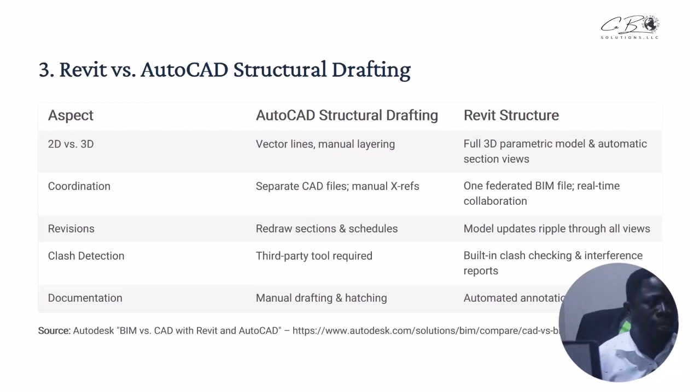Just some small steps. If you want your views, let's say your front elevation, these are not things we do manually in Revit. No, no, no, no. We don't do such stuff in Revit. Like you are done with your plan, you want to do your section. Just pick a section line, cut the section, and that's all. And then it will be there. The only thing Revit doesn't do for you is to list, for a section, that 50 by 150 timber rafter at 900 centers. Revit will not do that for you.